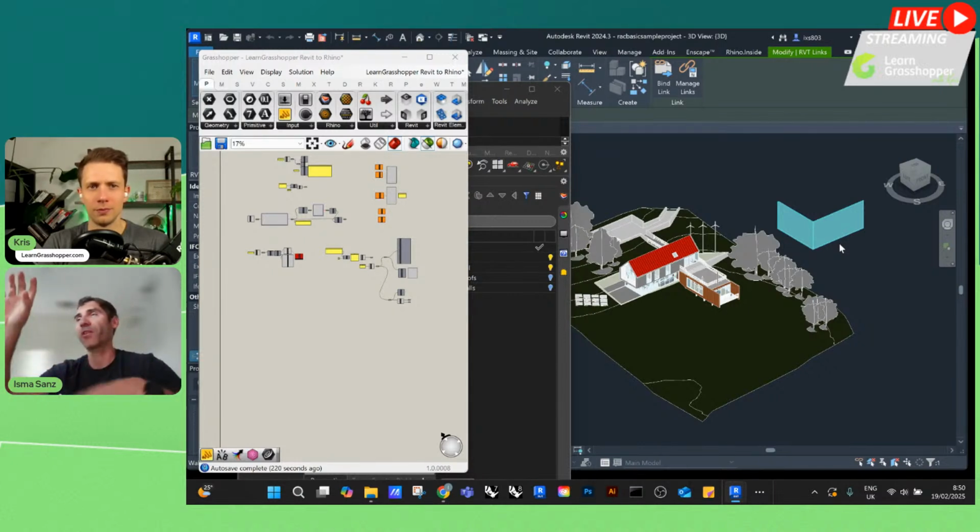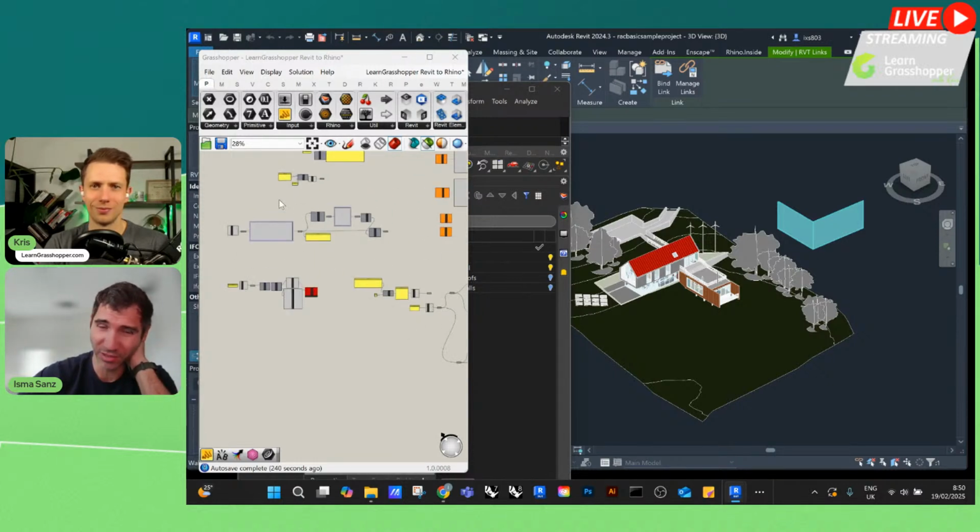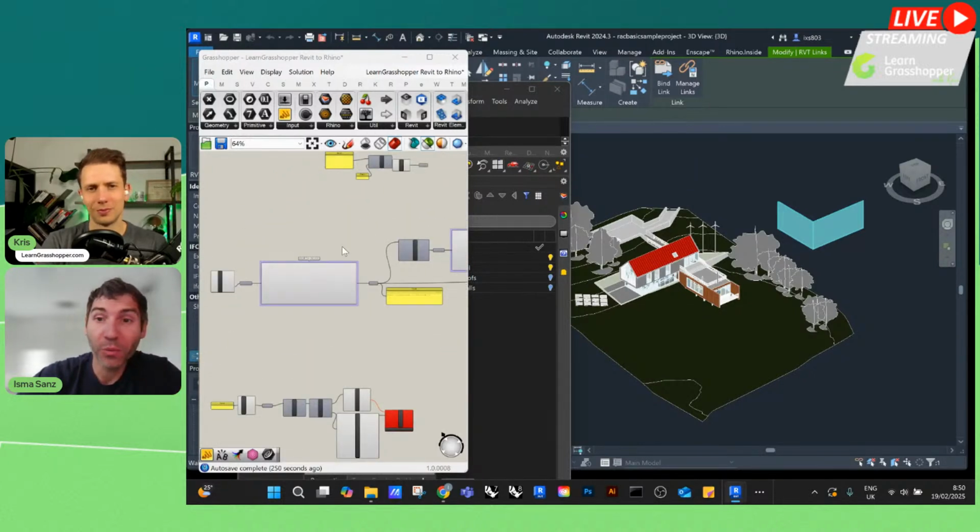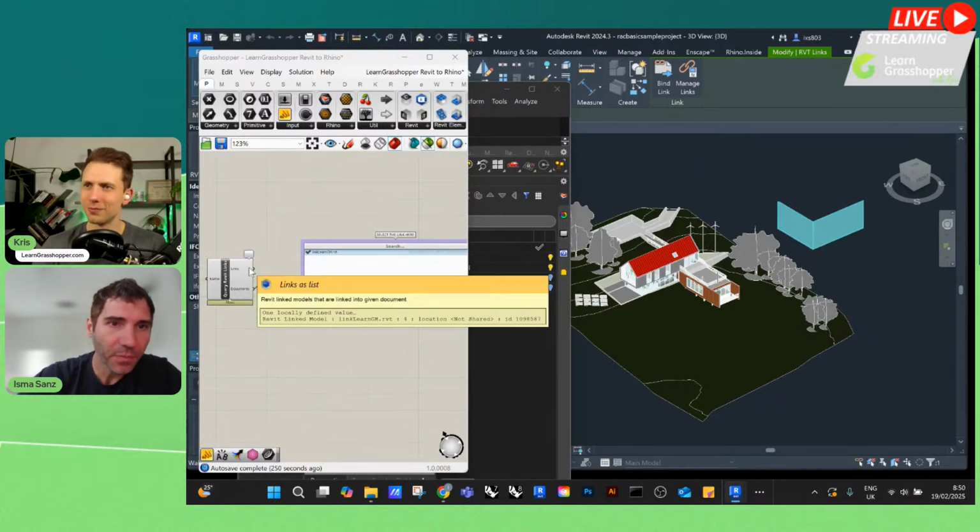But if they are in different locations, you can also extract the information, the origin, position, and the internal origin point from specific files. There's a component and rotation, and then you can do the transformation. But you should set up your Revit files properly when you're working with multiple files to make sure that you don't have many problems, because it could get very annoying for the people working with your files if you don't do it properly.